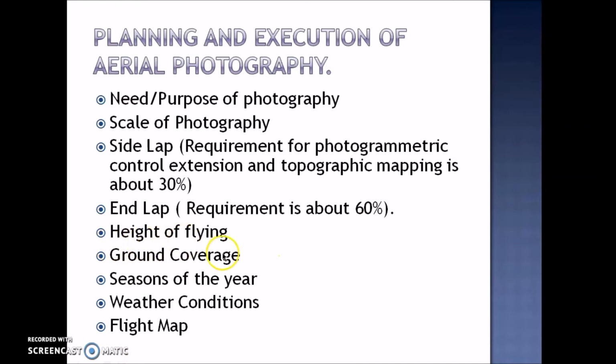The next one is height of flying. The height of flying is also a very important parameter. The height of flying for a project can be evaluated after the selection of camera and the scale of photography. The scale and the height of flying are almost inversely related. If the flying height is increased, the scale will decrease. If the flying height is decreased, the scale will increase.